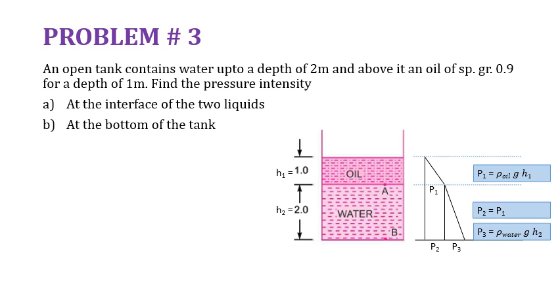of the tank. So we know pressure at any depth inside the liquid is given by hydrostatic law, which is pressure is equal to rho gh. So for the oil layer, where we have a free surface layer of oil, the pressure is simply rho gh. It is easy to compute at the interface. But at the bottom of the tank, the pressure would be because of both the layers, oil and water. And it is best understandable with the help of a pressure distribution diagram.